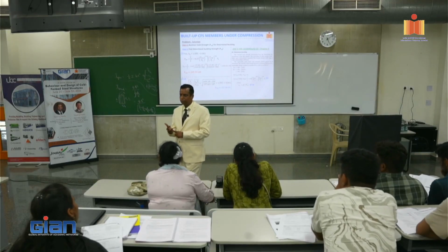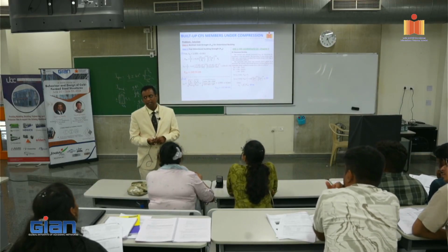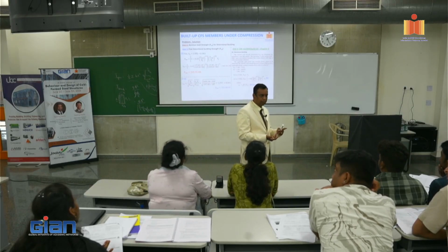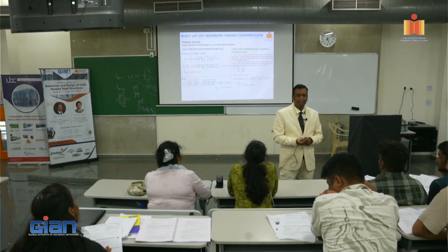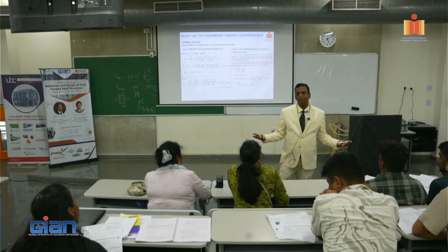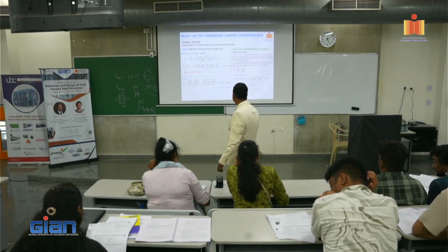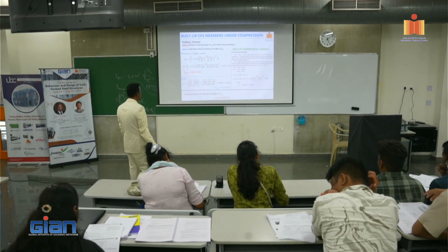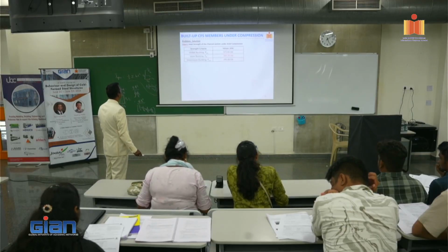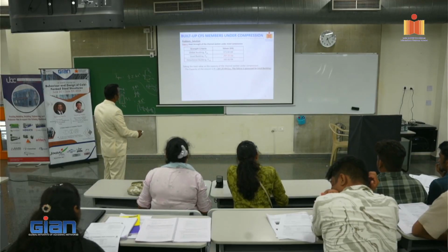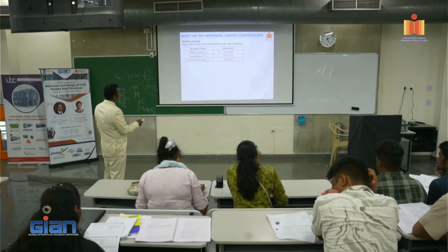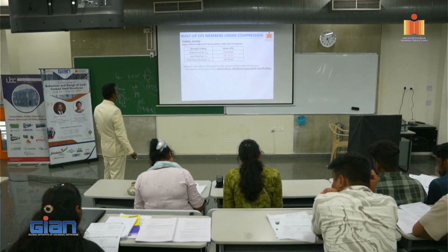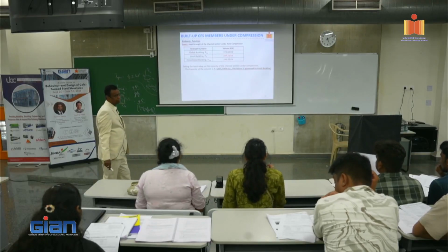The first portion is PNE. The second portion is PNL. The third portion is PND. Now which one is going to govern? We'll find out the minimum, right? So the distortional buckling strength is 245.92. So we have this one, 372.82, 207.2, this one. So the local buckling is going to govern. So this is the failure load.